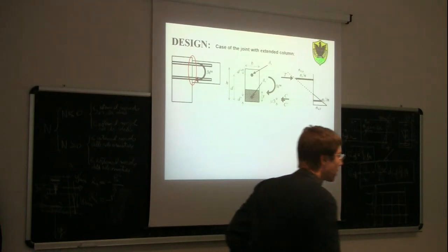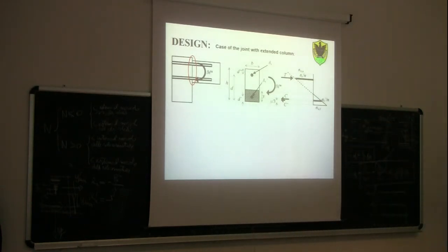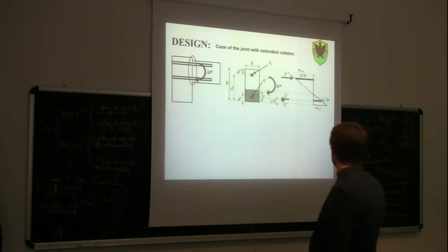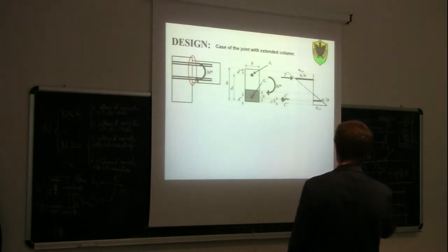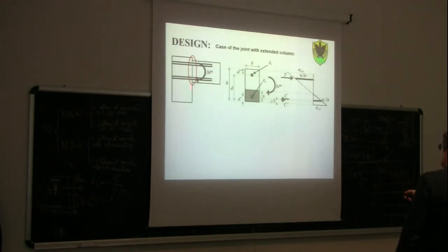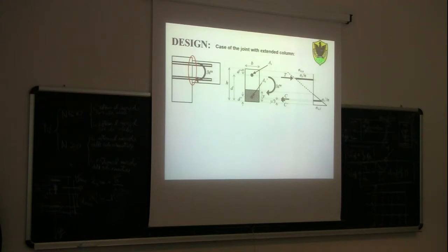If you remember talking about reinforced concrete, we make a distinction between what we call stage 1, uncracked cross-section, stage 2, cracked cross-section, and stage 3, ultimate limit state. So this is looking at this connection between a timber beam and a timber column. In this discontinuity section, we have a distribution of stresses which are linear, basically in timber, because we said that timber is more or less an elastic material, so we cannot expect having lots of plasticity in compression here.